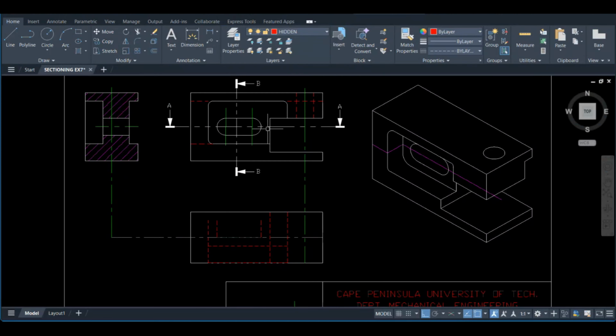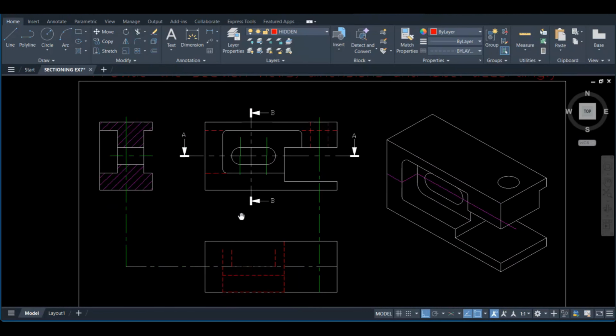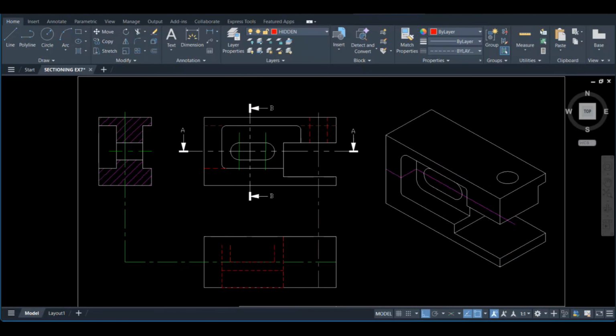So we're going to be left with the section that's only going to cut from here to there. Now this hidden detail is gone, right? Now the hidden detail from here, this guy up until there, gone. This guy until there, gone, right? So we're only left with this part here, like this. All right. And then, meaning that this becomes a what? A solid line.